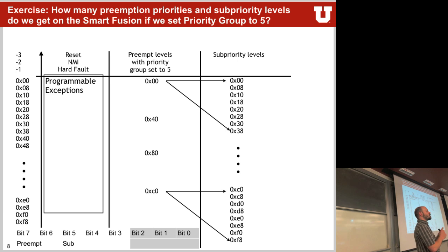That's implementation specific. So chip vendors don't have to implement all 8 bits of priority. In this particular case, this is the Cortex M3, where bit 0 through 2 are not implemented, so you cannot set them. That's where this comes from. Was that a confusion? Maybe?